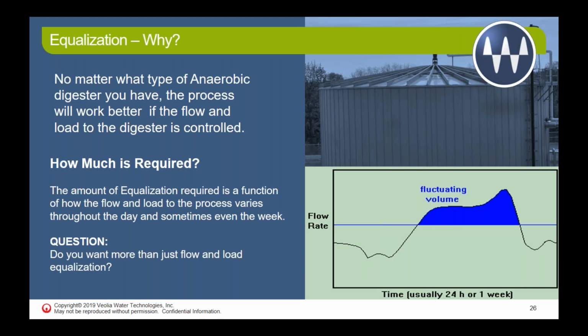You see the peaks and you see the dips in the flow throughout the 24-hour period, or let's say 12-hour period. So for us, in order to equalize the flow going into the system, we look at the distribution of those peaks and we say, well, if we apply a volumetric equalization of a certain time, we will be able to dampen out the low points and the high points in the flow and provide a steady volumetric flow to the downstream processes that do rely on steady volumetric flow without interruption in service.